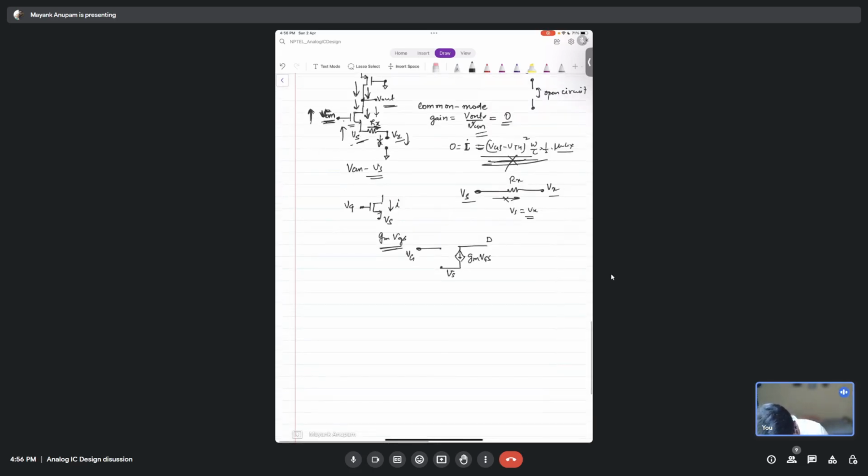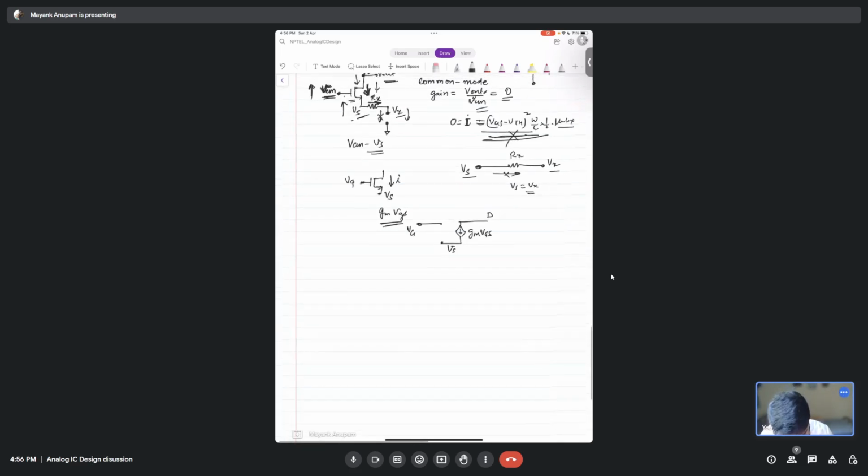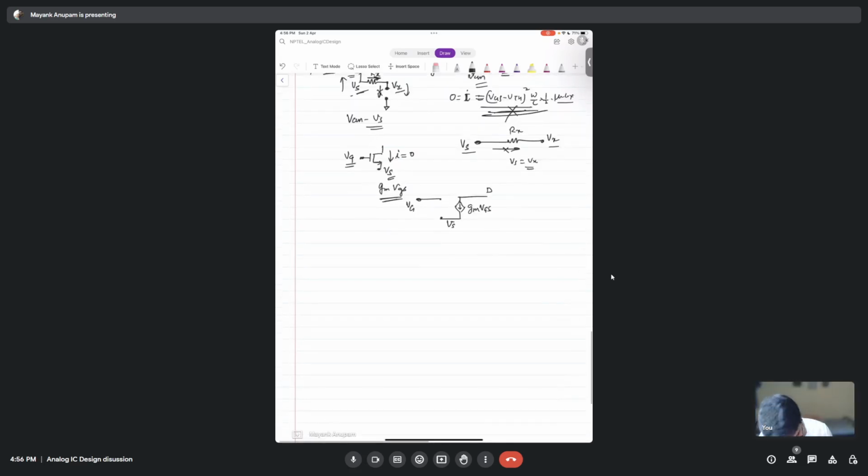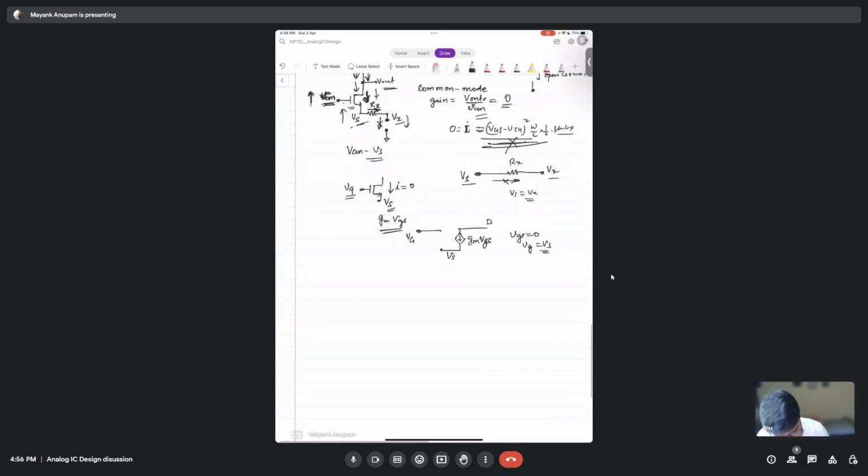But now, you only said that in this particular MOSFET here the current is zero, correct? There can be no current flowing here, right? So tell me, if the current is zero, what should be the Vg and Vs relation? It would be the same, sir. Equal. Correct. So they should be equal to each other, right? Because VGS has to be equal to 0. So VG has to be equal to VS, isn't it? Yes, sir.